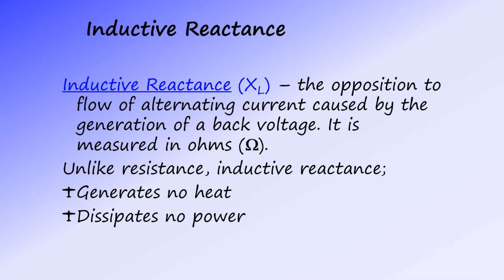Inductive reactance is the opposition to flow of alternating current caused by the generation of a back voltage. It is measured in ohms. Unlike resistance, inductive reactance generates no heat and dissipates no power.